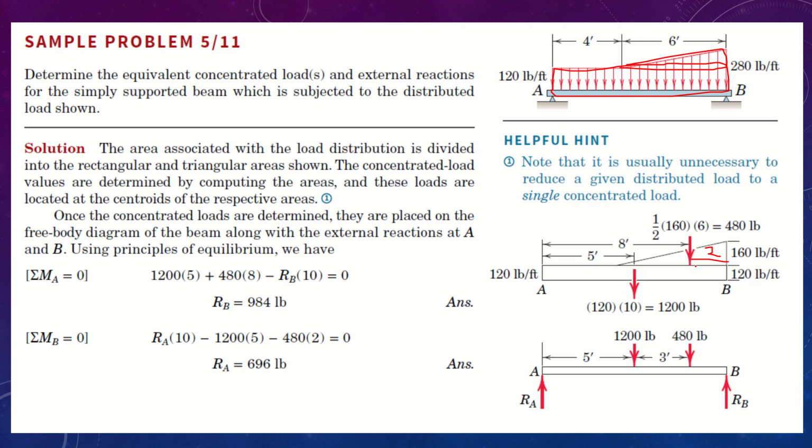Now you have two resultants and you have two reactions. One reaction is at A, the other reaction is at B. So the first equation is sum of forces acting upward should be equal and opposite to sum of forces acting downward. Now you can solve this by two techniques. The best way is saying the sum of forces acting upward equals the sum of forces acting downward. This will provide you with one equation, and it has two variables, so the two unknowns are A and B.